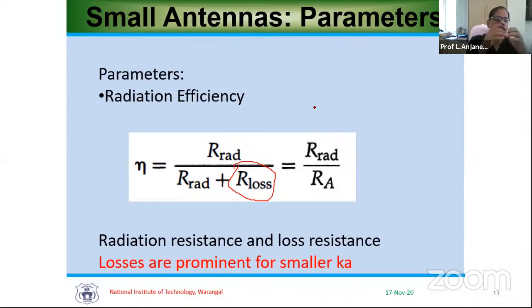So the circuit that you design will not work as per your predictions. Some may start leaking energy, some may start unnecessarily radiating energy, because they become unintentional radiators or unintentional radiating elements. It is because of these several issues that designing antennas at high frequency is very difficult. You will have a lot of issues, a lot of trial and error to make. There are several factors that you take into consideration when choosing the material for designing an antenna for a given application.